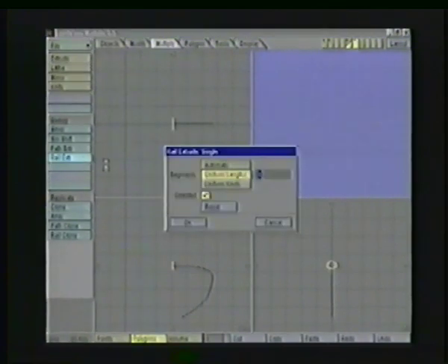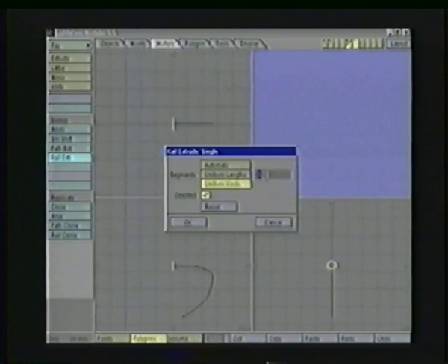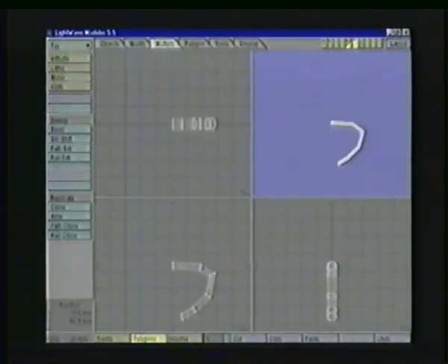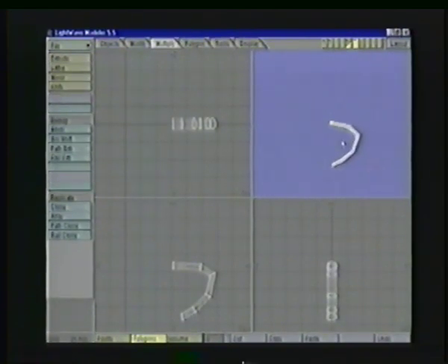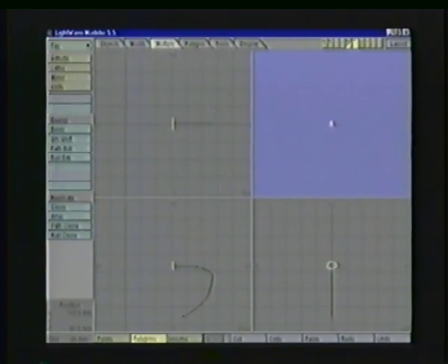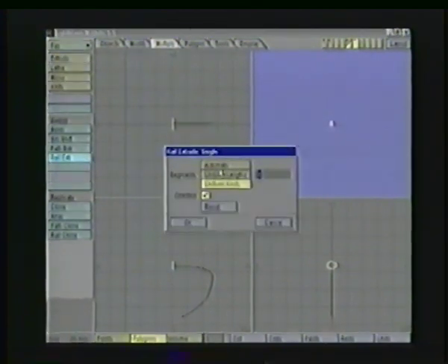So, if I use rail extrude uniform knots and give it 5 segments, it's put these 2 segments closer together because there were 2 points, or knots, on the curve. Now it's still not enough segments, but you can see how you'd get more control over where the segments are placed. I'm going to undo that one more time and go back to automatic.